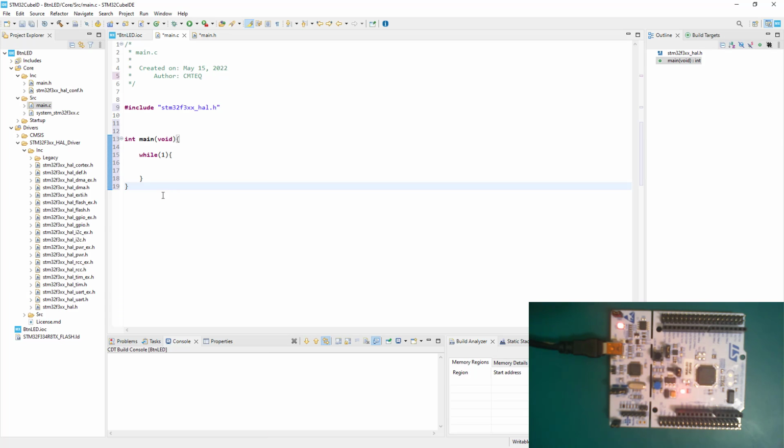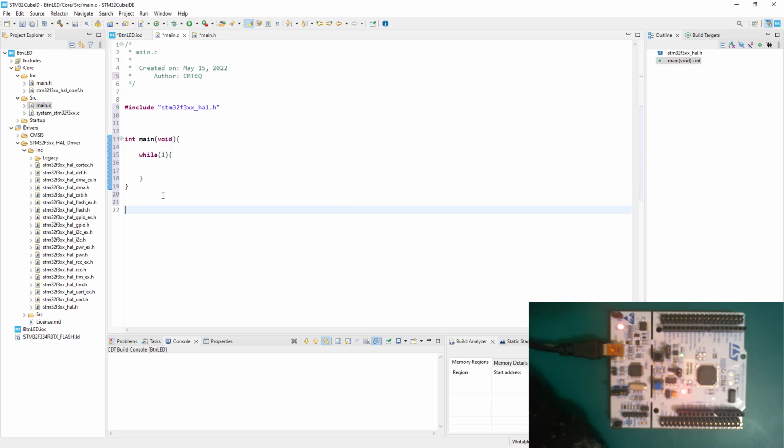Now let's go ahead and write a function that will do some pin configurations for our LED and push button. I'm now going to create a function of type void GPIO_config. This means I will be doing my basic configuration in this function. The function is not accepting any parameters, so I can also just pass void in there.